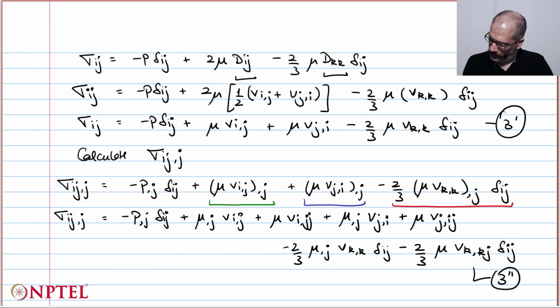So we have quite a few terms in this equation, but if I look at these terms, these two terms particularly, in fact, let's have this one as well, we can see that we have a spatial gradient of the dynamic viscosity mu in these terms. Now typically, for most of the fluids that we deal with, mu is homogeneous, because think about it, the fluid is well mixed. So there's no reason that the viscosity of the fluid should be more in some region as compared to the others.